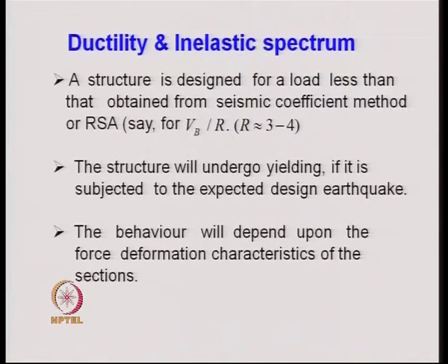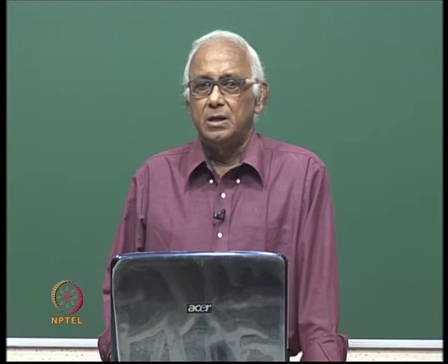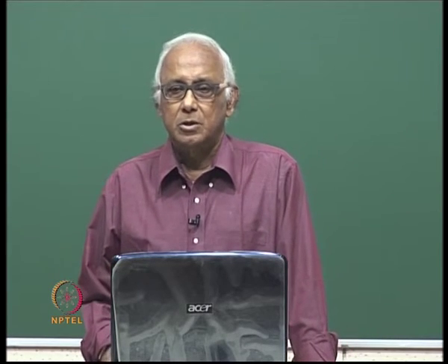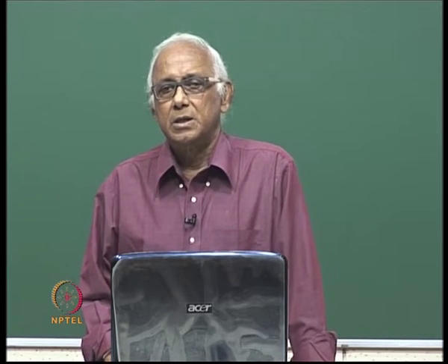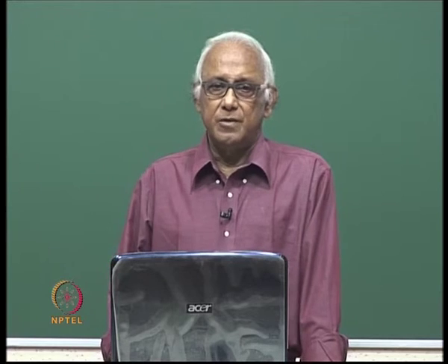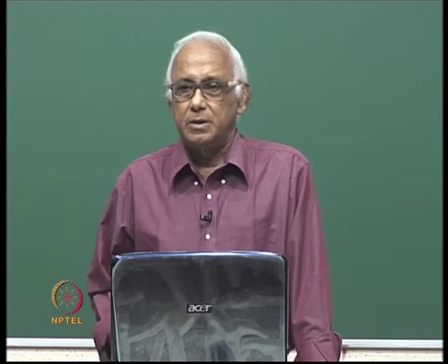Different elements go into the yield limit to different extent, and therefore, there is specific ductility demand which is imposed on the structure, not as an overall ductility demand, but a ductility demand which varies from element to element.